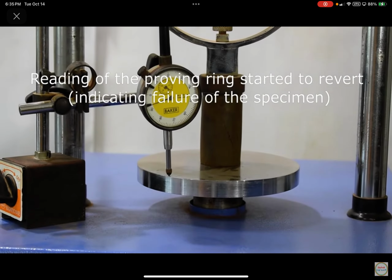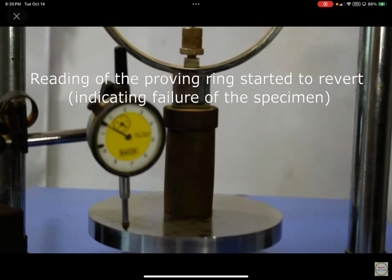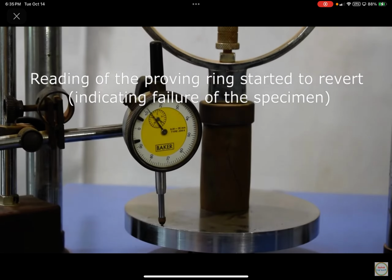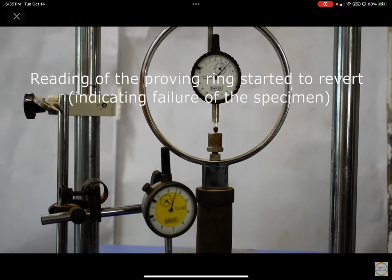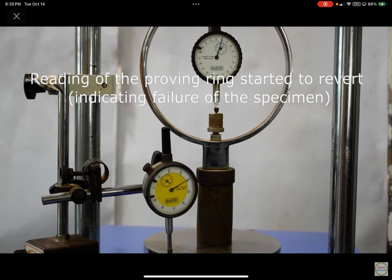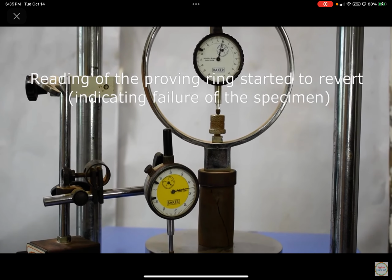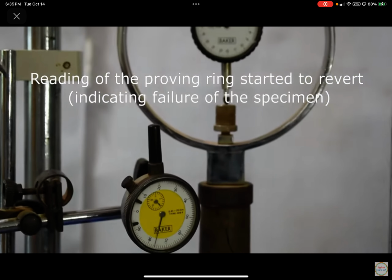Failure of the specimen looks like it's starting to occur. And if you take a really close look at the soil, you should see some type of crack begin to develop within the soil sample. And again, they moved the camera. But hopefully you see the crack develop within the soil. Now, is that perpendicular to where the load is applied, or is it at an angle? You'll notice it's at an angle. And by this point, the test is done.